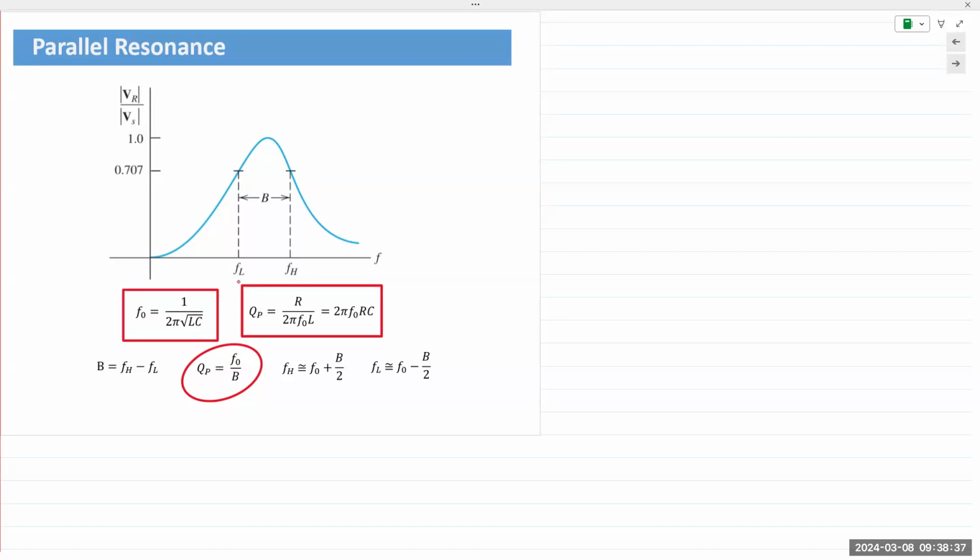Okay, the energy between the inductor and capacitor keeps being transferred between the two. And it's a concept we'll see again next week for reactive power. Okay, when you have a capacitor and inductor in the same circuit, the energy bounces between the two of them for an AC applied input.